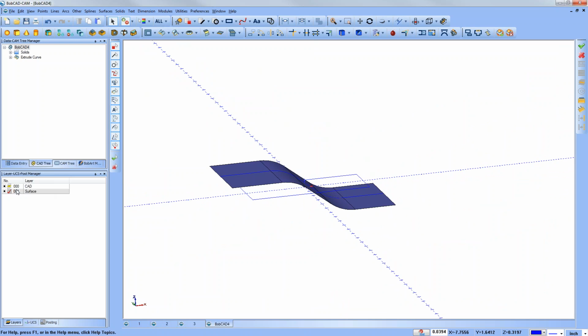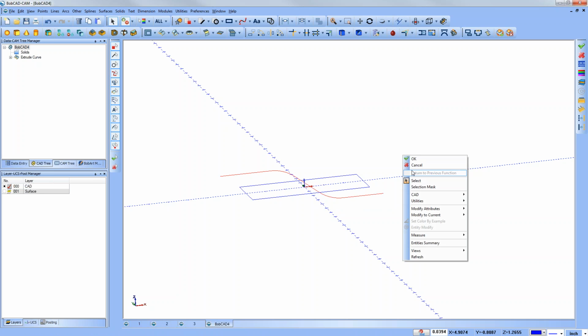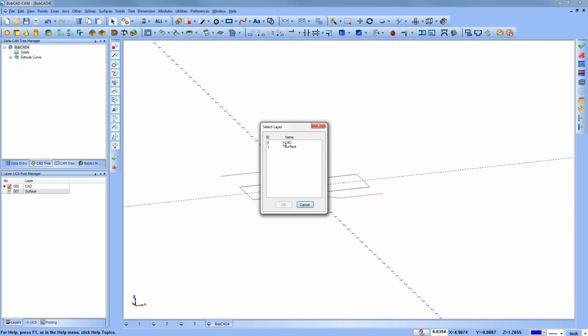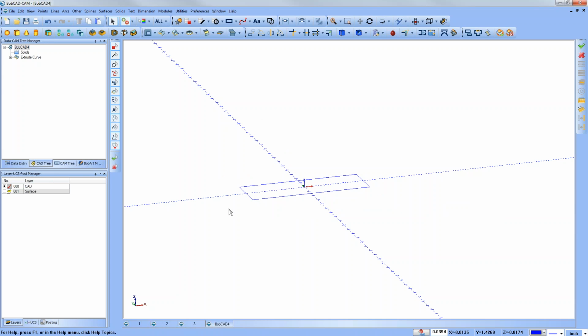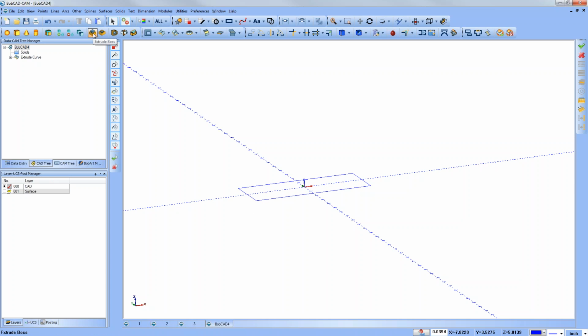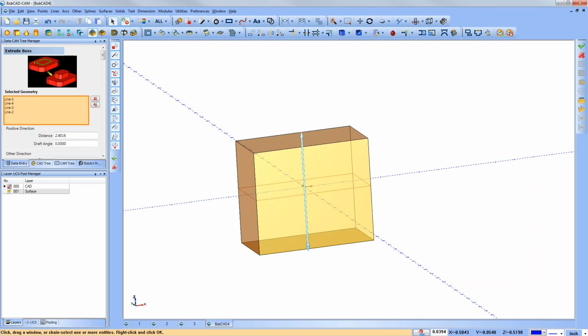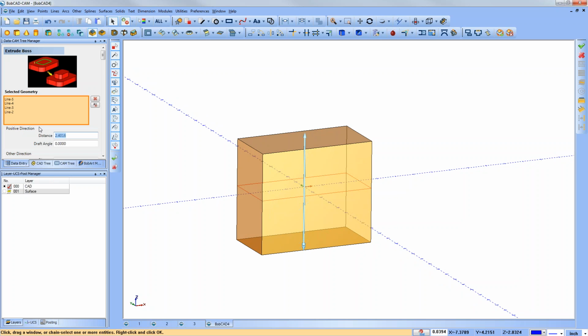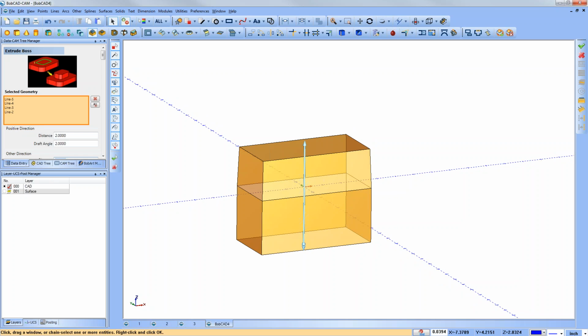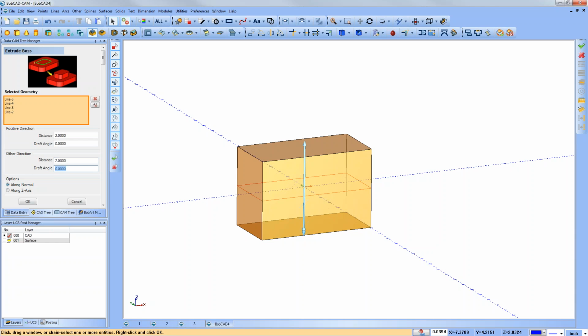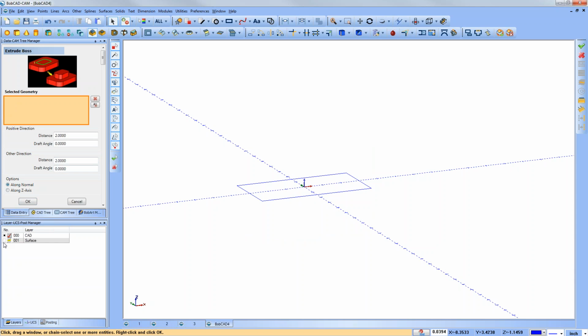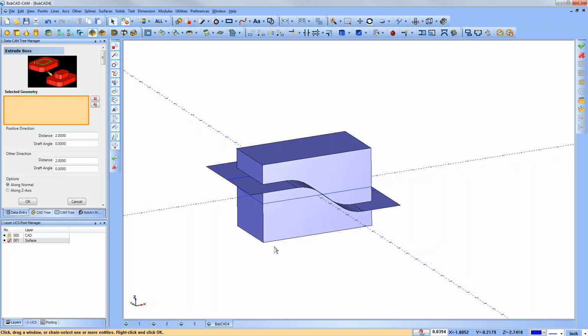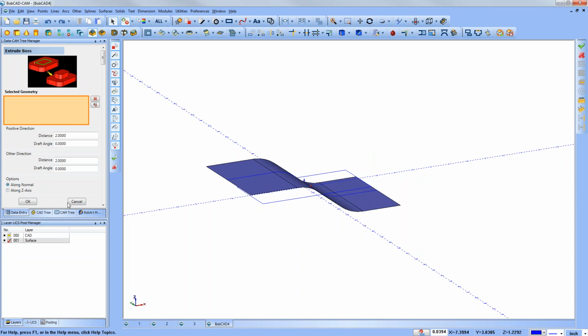And let me extrude this other part here. So I'll blank that. In fact, I'll put this on that other layer. Okay, get that out of the way. And let me use extrude boss in this case. Oh, no draft angle here. Kind of extend this so we can see. All right. Oh, you know what? I'll use extrude curve so it doesn't tie them together.